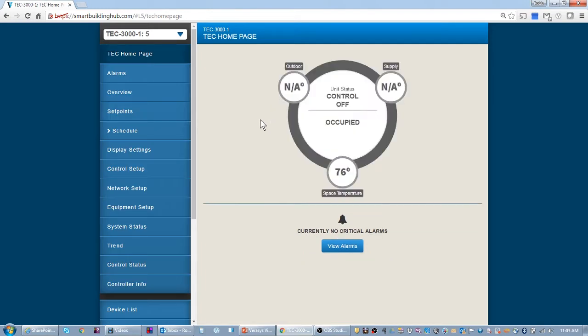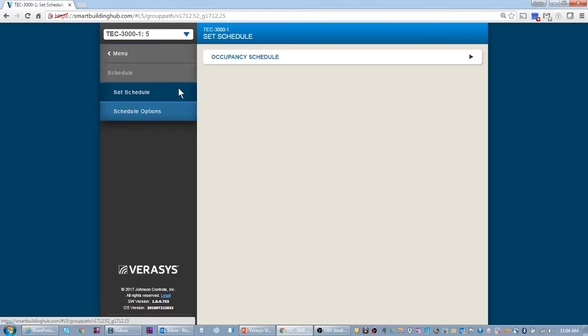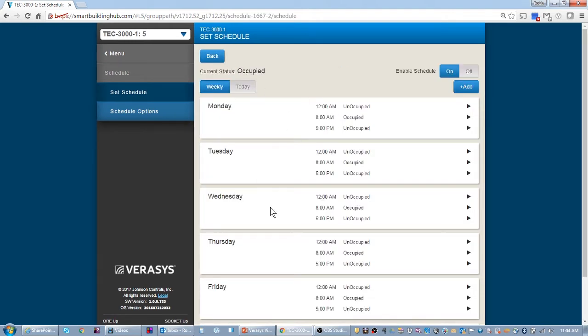So Verasys is one of the first building automations that is plug and play, that you can put these addresses anywhere between 4 to 127, and you just have to have an open address and it'll appear. So I'm going to go back to that schedule and just show you that that schedule is what we made earlier.